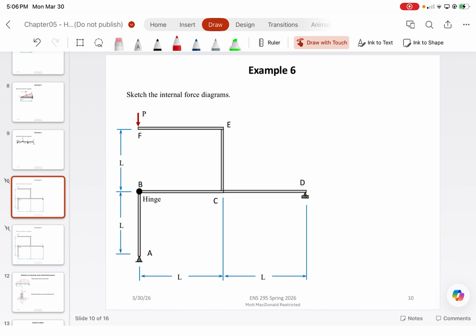Now what makes this complicated is the geometry and the fact that there are two dimensions associated with it instead of just one, right? This is where that reference fiber methodology that I was talking about last class really comes in handy. For beams, you might be wondering why even bother with the reference fiber. For frames, you want that because it helps you understand how the structure behaves as an entire global unit. So for this problem, I specifically made the reference fibers follow this path.